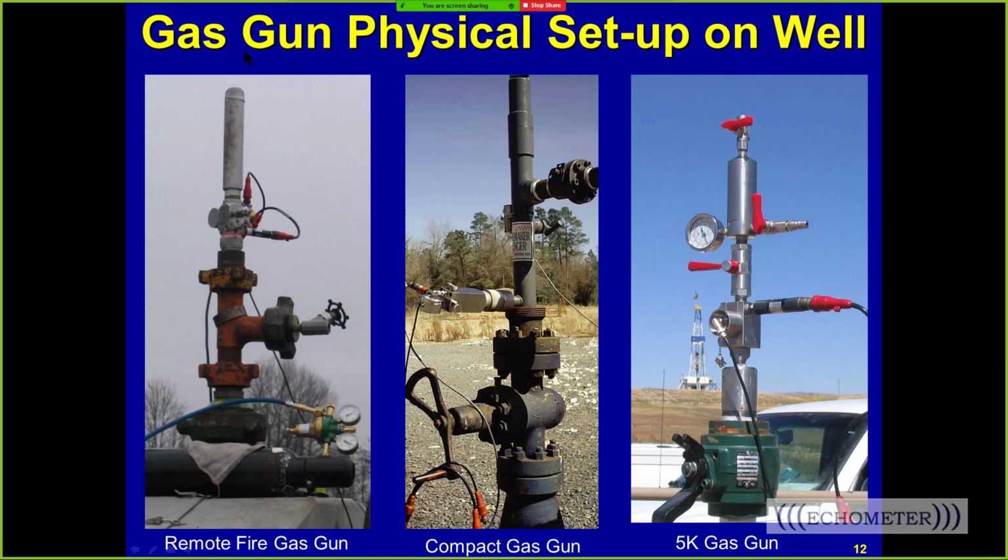In Holland there are a lot of people, and they decided that they needed to protect from any kind of release, and so in all the onshore wells in Holland, at the time I was there, they had installed a subsurface safety valve that reduced the height of the tubing by 2/3 from about a depth of 2,000 feet. So liquid would tend to accumulate on that subsurface safety valve, and often they couldn't shoot past it.